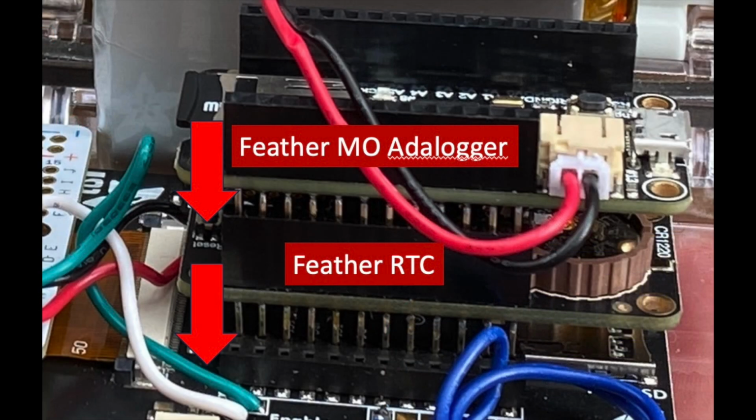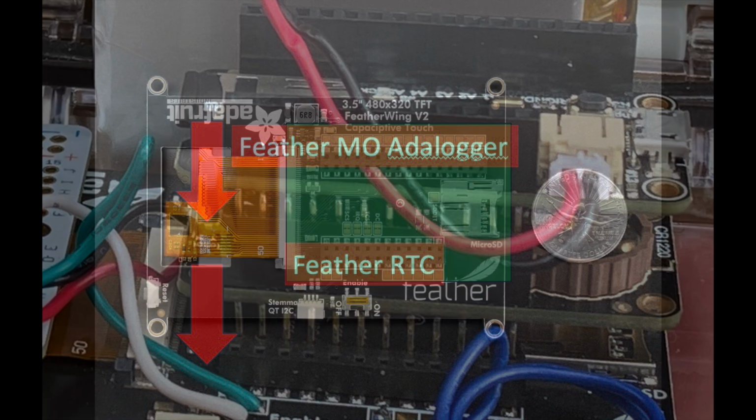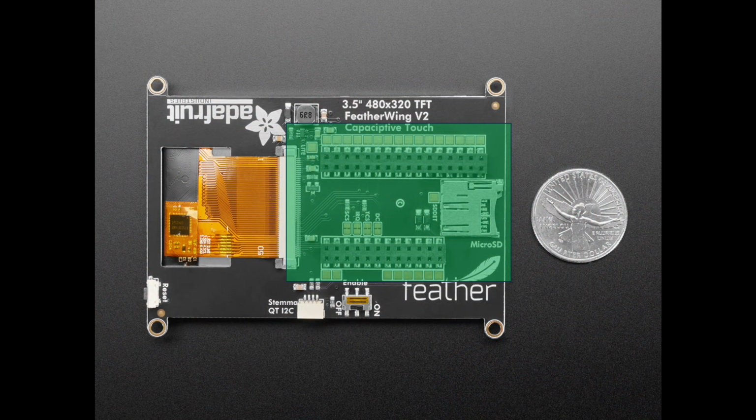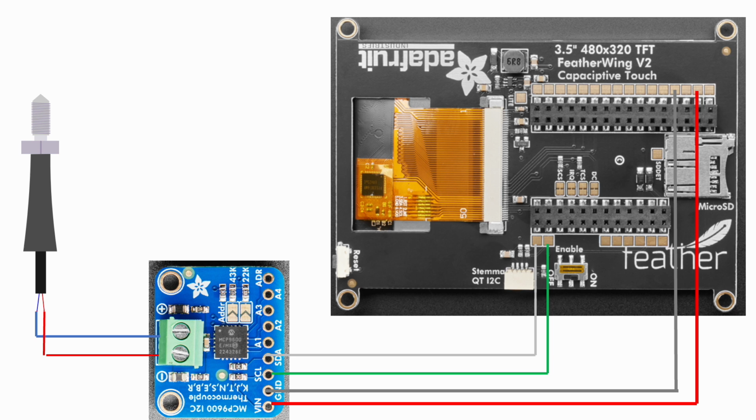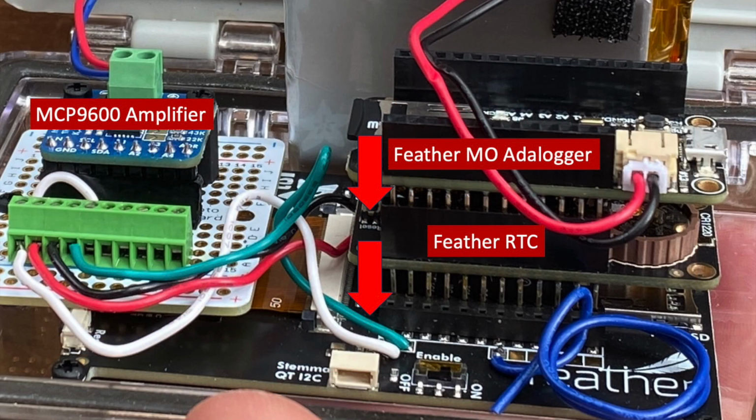Regarding wiring, the Feather M0 data logger and the real-time clock plug in directly into one another, and then seat directly on our 3.5-inch TFT screen via these female socket headers on the back of the display. This image shows how the remainder of the wiring is addressed between the screen, the thermocouple amplifier, and the thermocouple itself, which communicates over a protocol known as I2C with the microcontroller. This image shows how everything is wired up in our own setup using a protoboard and terminal block to facilitate connections between the thermocouple, the amplifier, and our TFT screen.